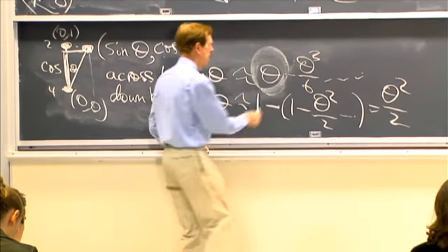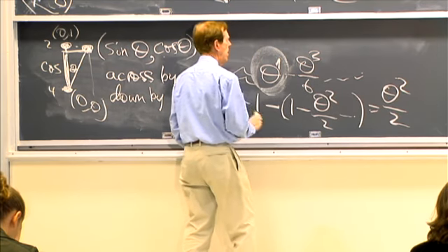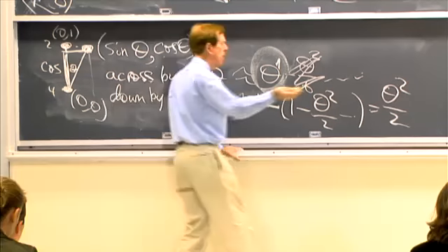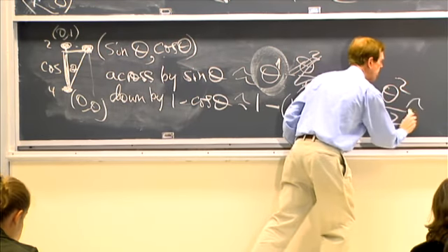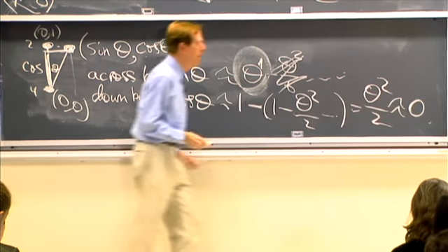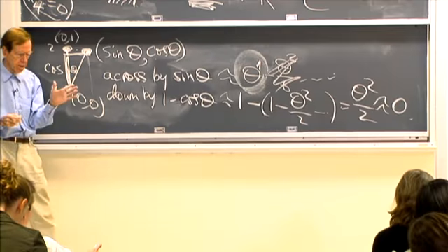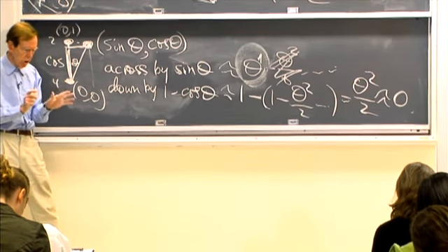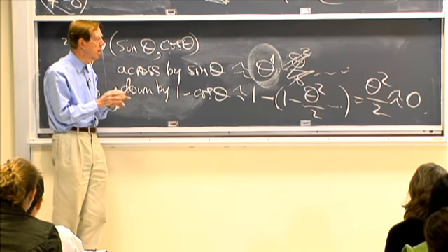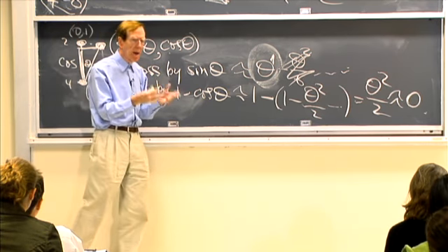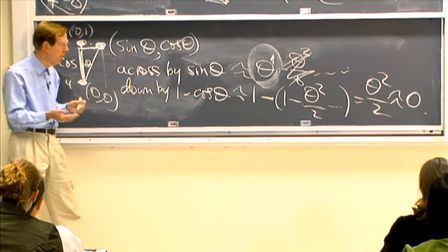So here was theta to the first power. Theta cubed we didn't care about, and we don't care about theta squared. So that's why it's 0, because it's a second order movement, right? If theta is small, as I'm going to assume, small displacements, if I allowed theta squared and cos theta in here, I'd have a nonlinear problem.